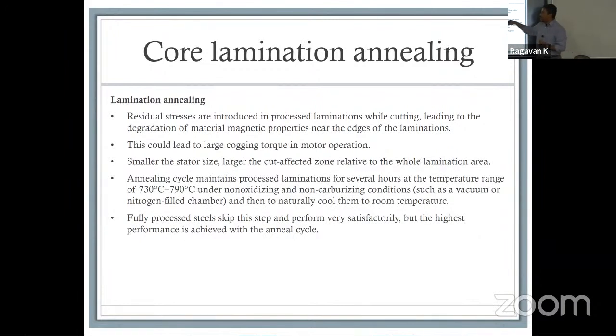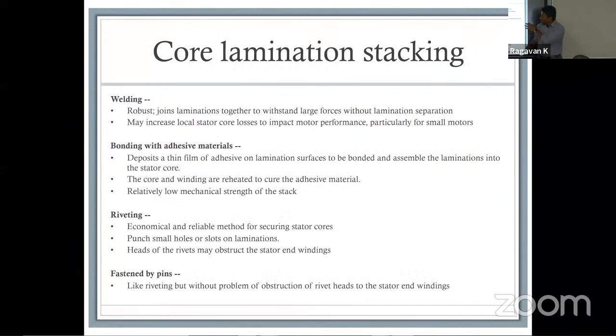So if you're talking about a small stator size, in that case, a larger cut affected zone can have a very significant impact on how your motor behaves. It can have a very significant impact on how many laminations you can stack. So the stacking is basically what comes back. You have welding, bonding, riveting, or fastening by pins. The names are self-descriptive, right? They actually tell you how you're supposed to put them together.